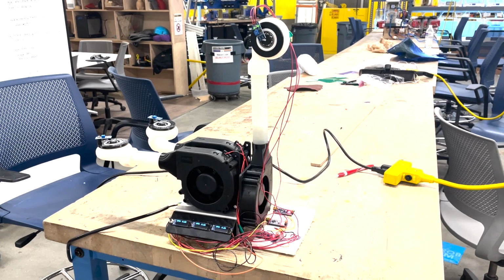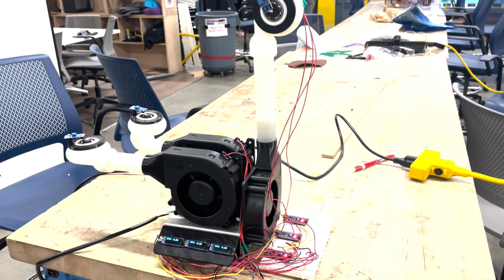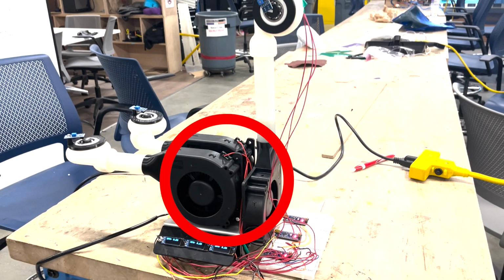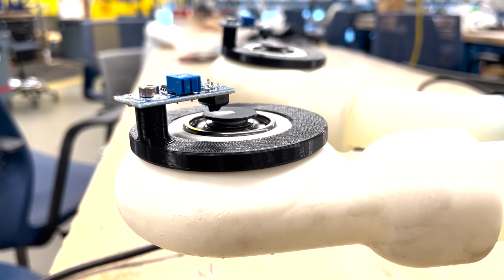The experimental setup includes 3 different iterations of a duct tube with a distinct feature that contributes to the overall loss. The first tube has a straight, smooth structure with different inlet and outlet heights. The second tube has interior roughness, and the third tube has a bend, although the last two maintain the same inlet and outlet heights. A fan connects to the base of these tubes to provide airflow, which a self-assembled anemometer measures at the top of the tube.